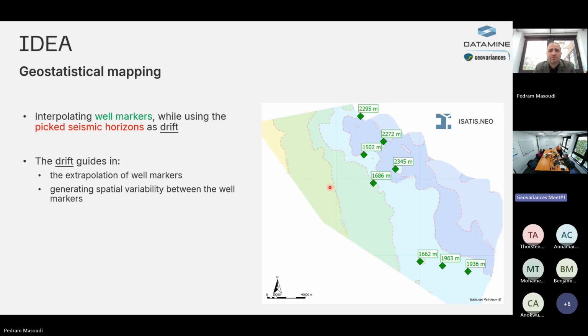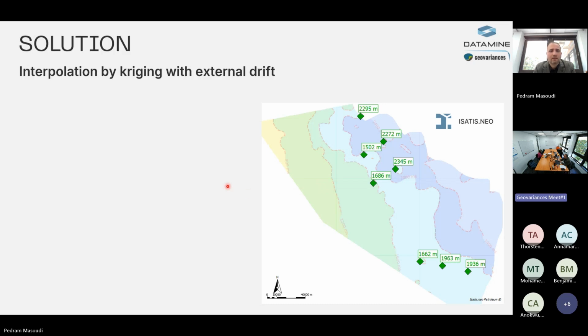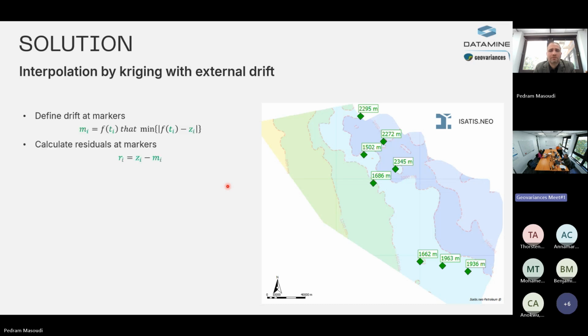The methodology that I'm going to show is not co-kriging, is something related to universal kriging. As you know, in the universal kriging, or another name is called kriging with external drift, there is a very tiny difference between these two methodologies, external drift and also universal kriging. In one of them, the drift or the trend is inferred. In the other one, the drift or trend is not inferred, but is calculated by the user. But the main idea is the same.